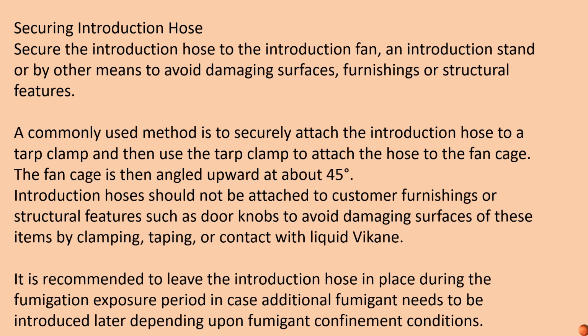Introduction hoses should not be attached to customer furnishings or structural features such as doorknobs, to avoid damaging surfaces of these items by clamping, taping, or contact with liquid Vikane. It is recommended to leave the introduction hose in place during the fumigation exposure period in case additional fumigants need to be introduced later depending upon the fumigant confinement condition.